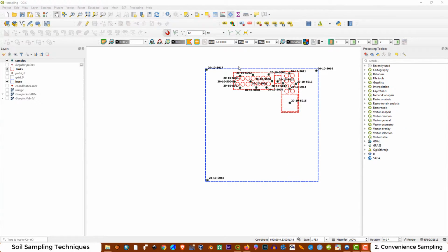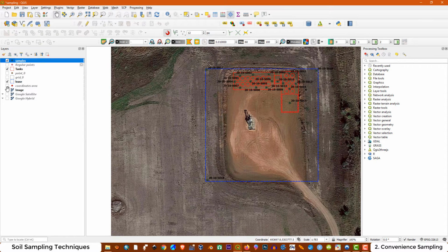What I am going to do now is digitalize the access road, the berm area, and also the well center. When they are making the oil and gas fields, they try to make this area quite flat and very smooth, just to facilitate the access of the vehicles and the trucks, etc. What they do is strip all this area with excavators and accumulate the topsoil at the berm area. And it's this kind of structure that you can see in the satellite image.